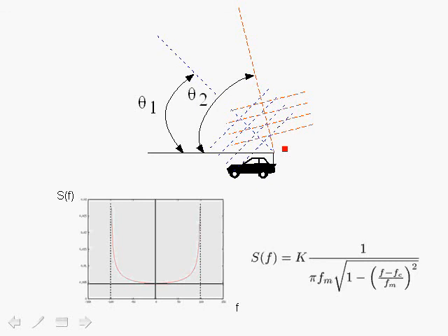However, the narrow-band Gaussian random process centered around the carrier frequency has a power spectral density as expressed by this expression here that we derived, and exhibits a Doppler spread. But in the time domain, it is represented by a narrow-band Gaussian random process, which we will investigate next.